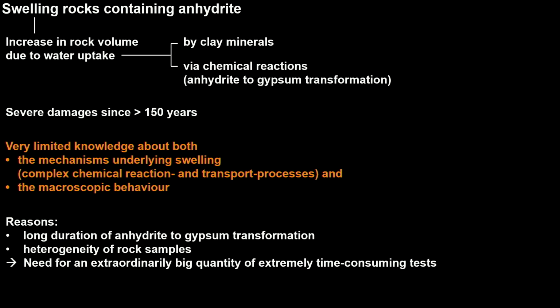The reason is that even at the scale of laboratory specimens, we need a long duration for swelling tests, in order for the anhydrite to gypsum transformation to achieve an equilibrium so that no more changes are observed. So at the scale of the laboratory, we are speaking of years to decades.